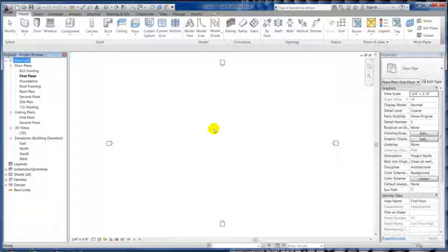They won't plot. You can name them. A pretty good rule of thumb, if you want a reference plane to be kept: for instance, if you cut a structural member to a reference plane and you delete that reference plane, the cut goes along with it, so the structural member will go back to the way it was. That's for doing angles and such. If you want to keep it, it's a good idea to start naming it. A lot of firms do this. If it's not named, it's fair game to be deleted because the other guy working on the project behind you has no idea what it's for. So get into a good habit of using reference planes and naming them if you want them to be kept. If not, you can delete them after you're done.